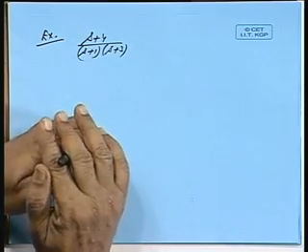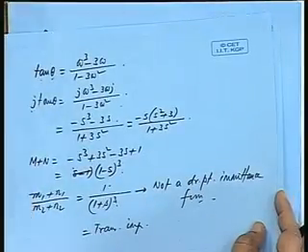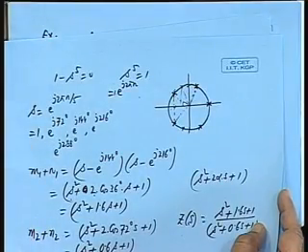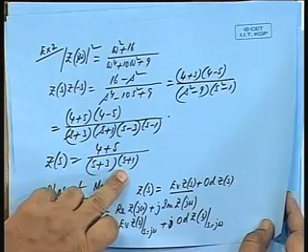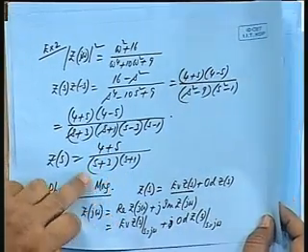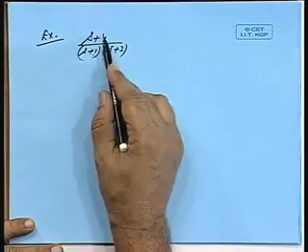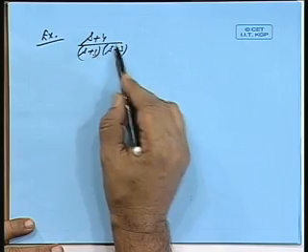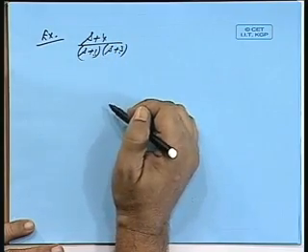This is a function which we got just some time back, if you remember, the first example that I worked out. Yes, this is the one, (s plus 4) by (s plus 3) into (s plus 1). So, how to realize this? It is a positive real function, though poles and zeros are not coming alternately. There are two poles first, then the zero. So, it is neither RL nor RC.